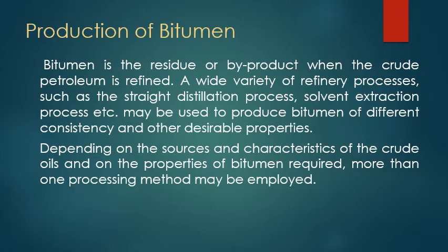The mixing temperature with the aggregate also varies slightly, but it is nearly 160 degrees Celsius, and that is maintained and monitored in hot bituminous mixing plants, right?